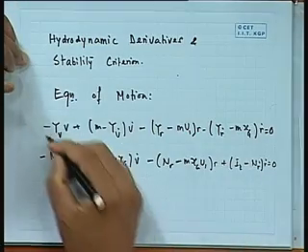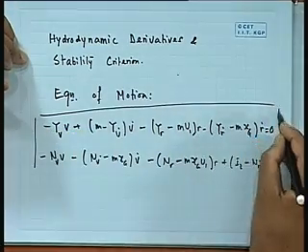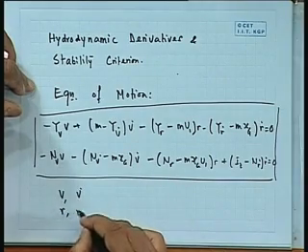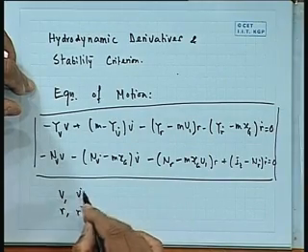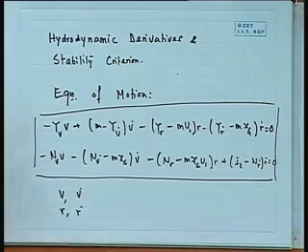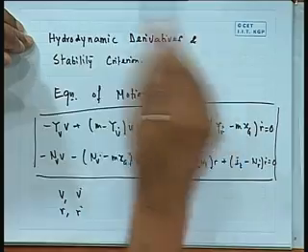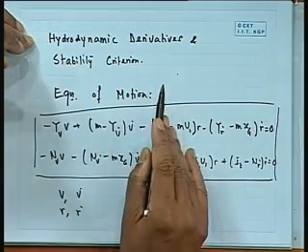See, we had these two sets of equations yesterday that we have found out represent a body or a shape moving initially along a straight line and disturbed slightly. They are governed by this equation, where v and v dot, r and r dot are sway velocity, sway acceleration, yaw velocity, yaw acceleration. Now, what is meant by stability criteria, and of course, I will talk about the hydrodynamic derivative also, is